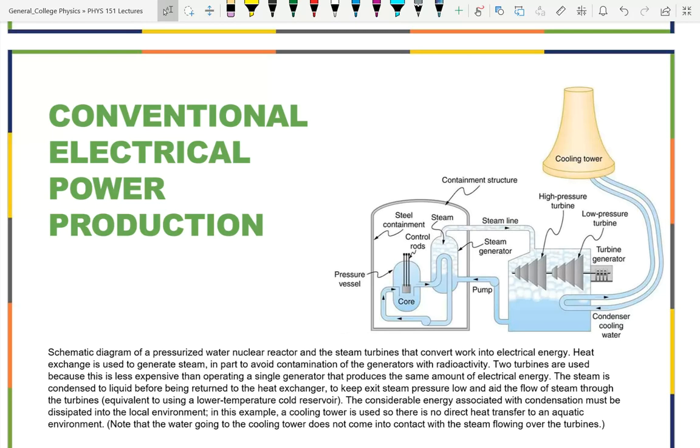So you can, for instance, build this on the side of a water body, and you just bring in stream water or ocean water, whatever, and use that ocean water as the cooling water that goes into the cooling tower. And you have your isolated water in the steam system that is ultra clean. So when you look at power plants, you almost always find them on bodies of water so they can use that water as part of their cooling system.